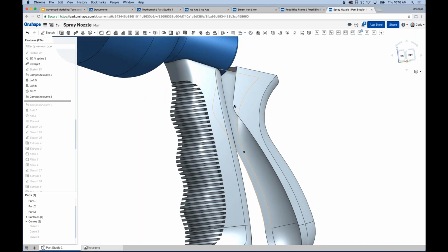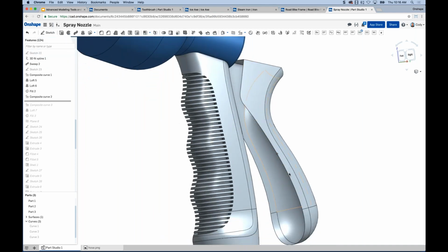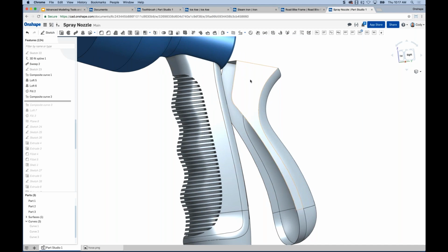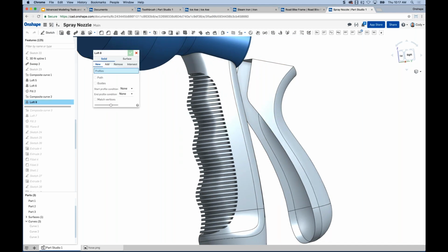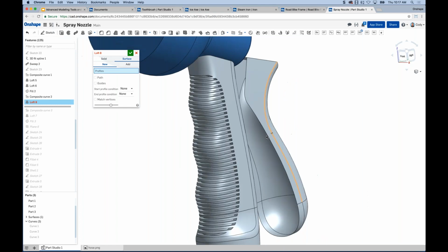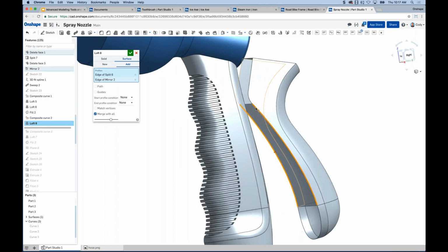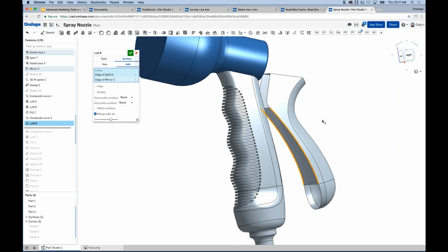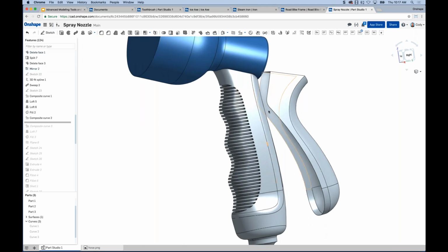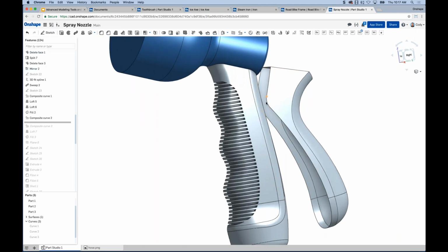And what I really want to do is enclose this back section of the surfaces, but I only want to do it up to this point. I want to leave this bottom piece open for another feature later. So I want to loft closed all of this. Now, if I select loft, and we choose surface here, and I left click an edge, and I left click an edge, you can see that I can go through and loft these, but I'm going to create a whole bunch of them. I need one here, and I need another one here, and that's if I'm using edges. If I'm using other things as well, I would need to create a series of these. So it's not really ideal. What I want is one loft that closes this entire section.